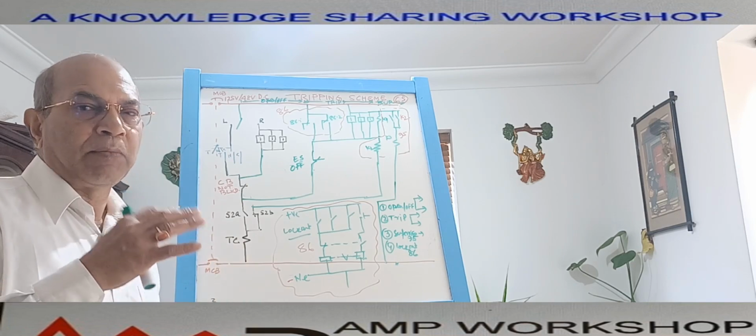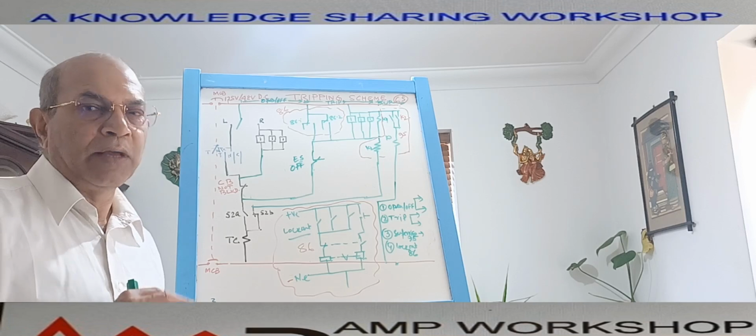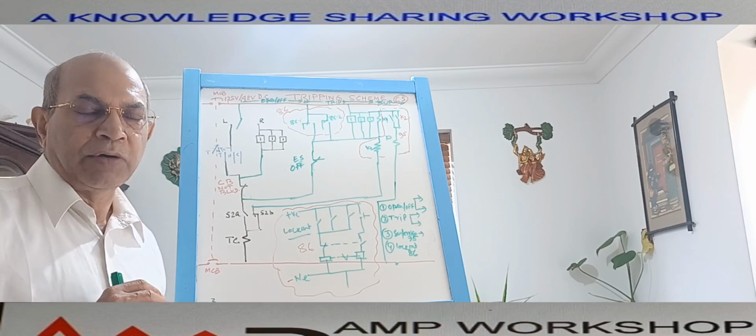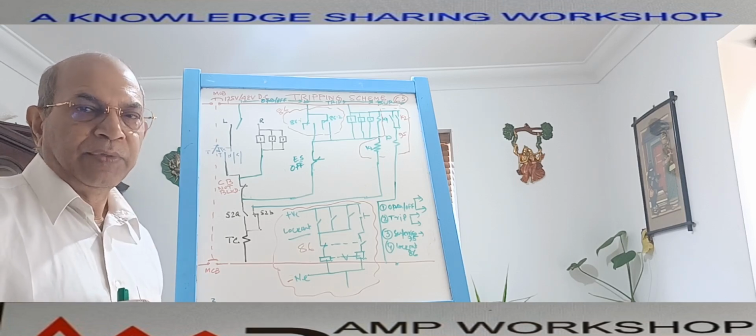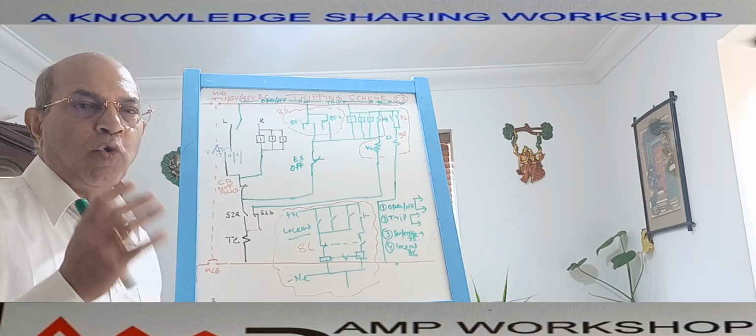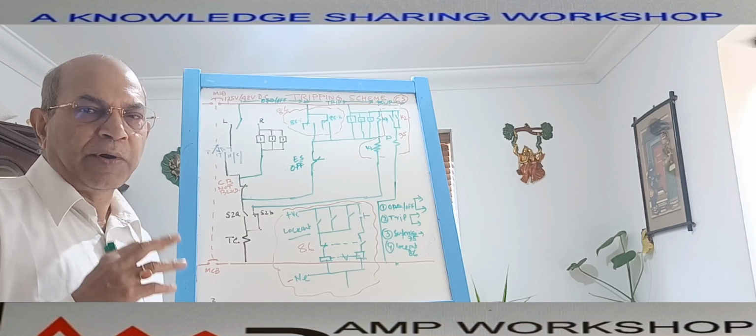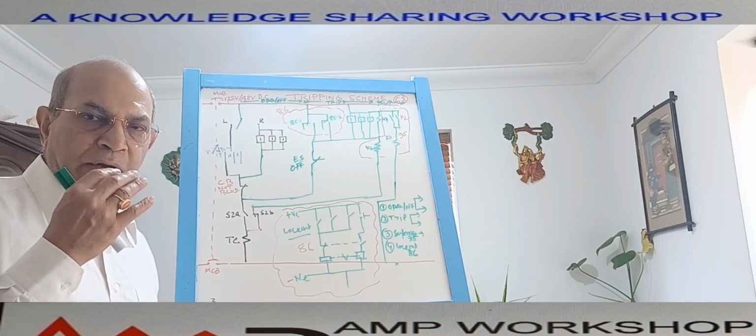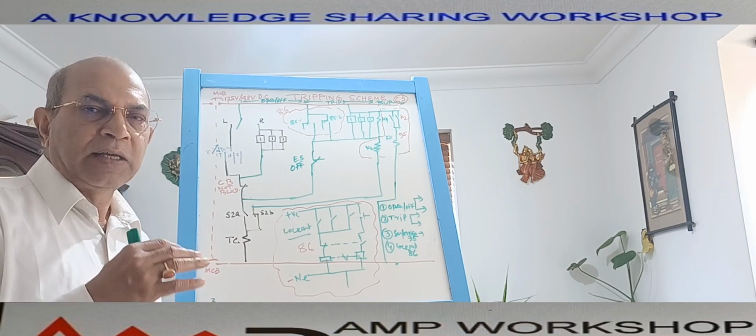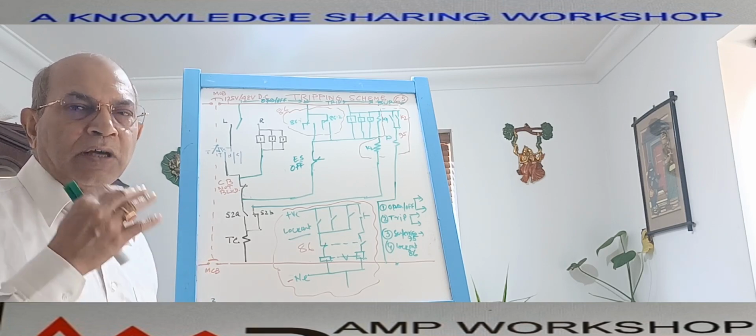If the breaker opens under that abnormal condition, we do not call it an open operation, we call it a trip operation. That's why we divide the opening of the circuit breaker into two conditions. One is a normal manual open, under normal healthy conditions of the circuit or the remote end.